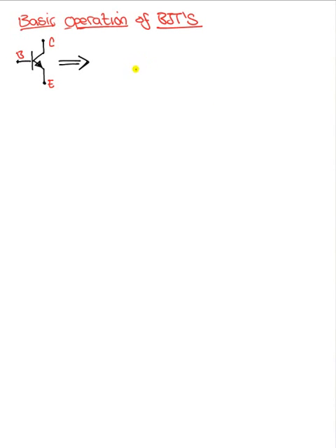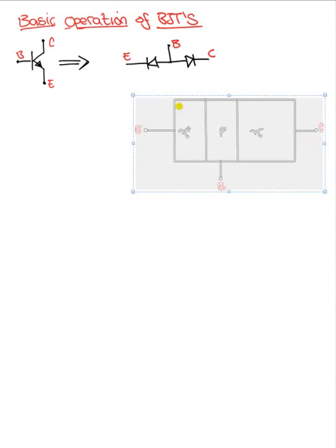So you have, this is the back-to-back diode model that a lot of times they use for large signal DC analysis. And so you've got the base, emitter, and then collector, and then on the bottom we'll put a visual model of how the semiconductor device will actually look, right?